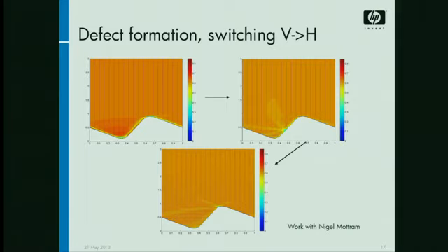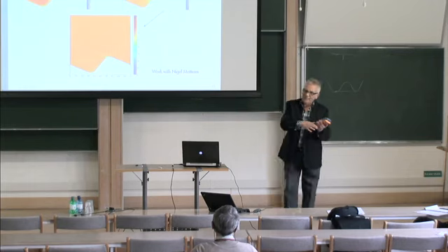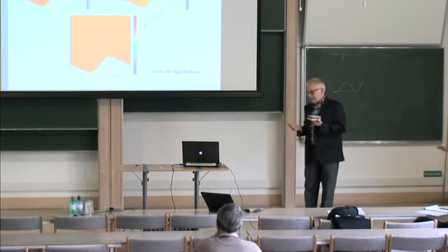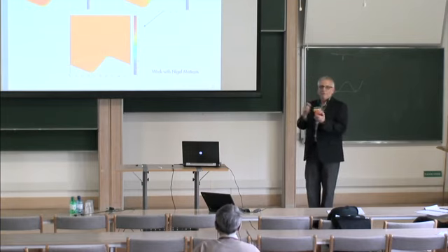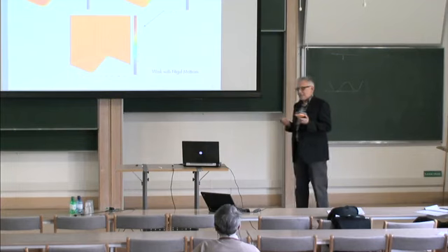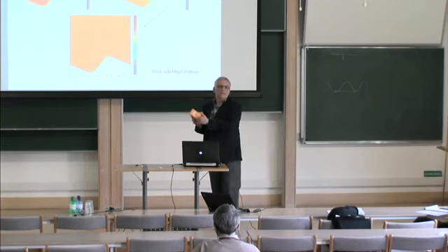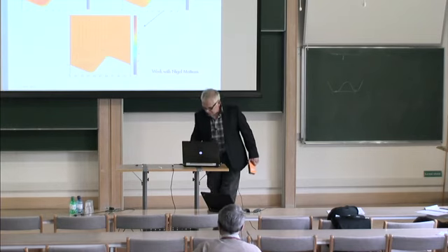That was useful because we could then go to the liquid crystal manufacturers and say, we want a liquid crystal which has a lower dielectric anisotropy, because there's a trade-off between the dielectric anisotropy and the flexoelectricity terms, and which has high flexoelectricity. We were able to get a range of materials from them with those sorts of properties and find, in fact, better materials to use in our cells. So by understanding what was going on, we were able to make some progress.